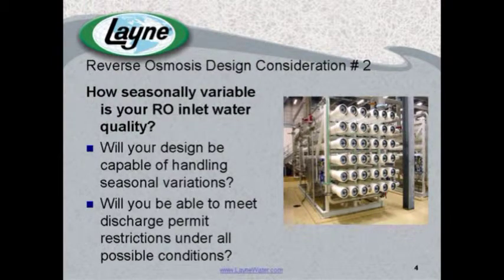We have seen situations where, because of drought conditions, say in the summertime, you are discharging an extremely high amount of extremely high conductivity water at the end of your reverse osmosis stream in your reject water. And in fact, we've had situations where clients have come to us and with their current designs have not been able to discharge that water because they would be violating their NPDES permit.